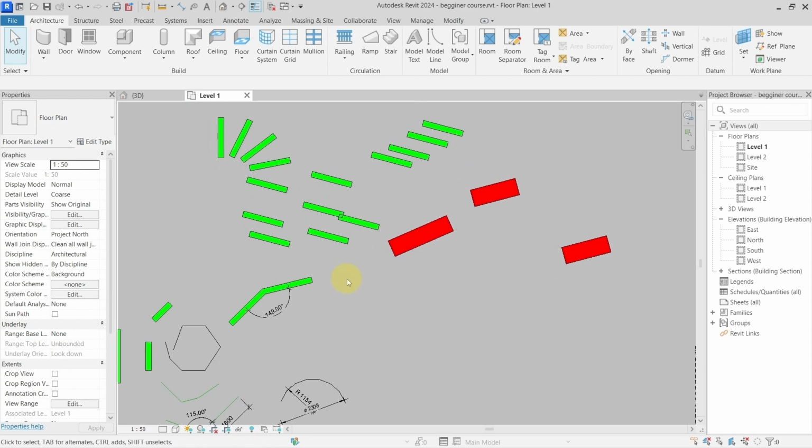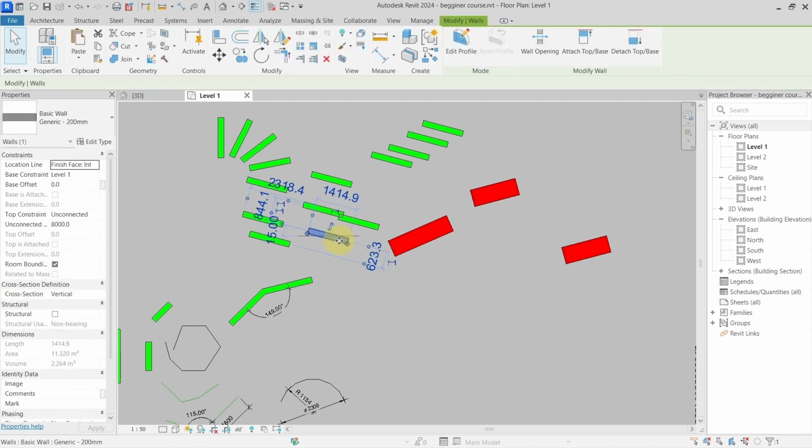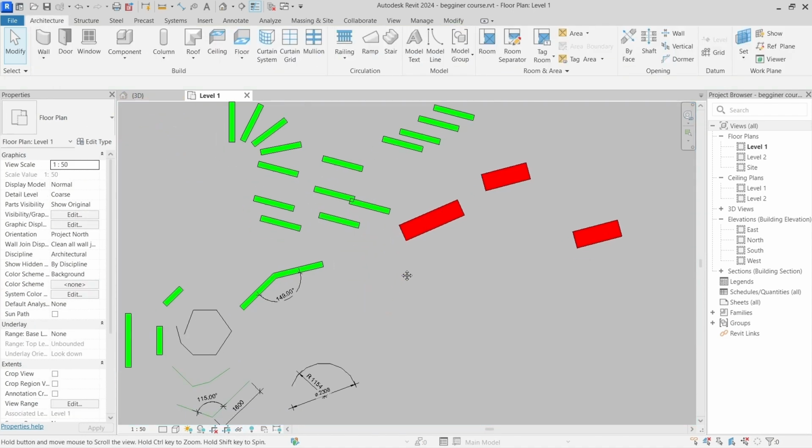Now let's go with the IC shortcut, which is for isolate category. So if I select my wall, now again we go with our categories, which can be found here. This is a wall category. So if I now will isolate only the things that go under this category, if I go with my IC shortcut, you can see that my dimensions and my detail and model lines disappeared. I can go again, because this is this bluish temporary hide isolate mode, with HR back to my view.